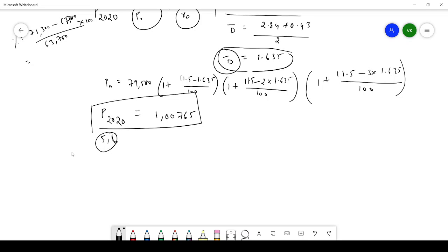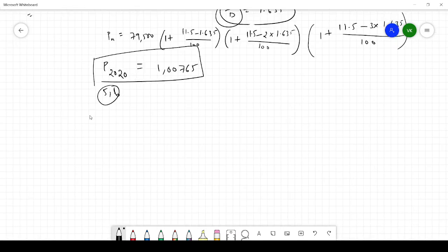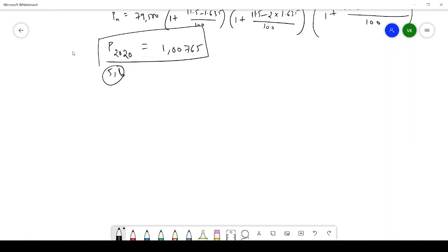You don't have any problems on that. So why are we studying all these population forecasting techniques? Because if you want to design a system, first we have to fix the discharge value. As I told in the previous lecture, the discharge depends on population, I mean future population, water demand, and design period. These are the 3 factors on which our discharge depends.